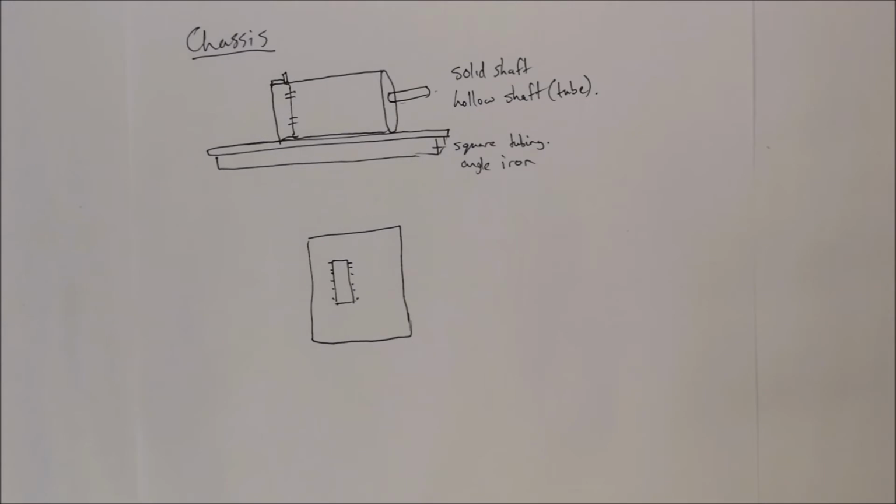But you might find that also there's not much forces acting on electronics. So your electronic box can be made out of plastic. It'll be strong enough, but the structure around it, the chassis that the electronic box is going to be mounted on, that could be a different situation. That might need to be some strong material, because there could be other motors on it and stuff, and therefore you might use your mild steel. But your electronic box will not have to be that strong, because there's no forces acting on that specific electronic box.